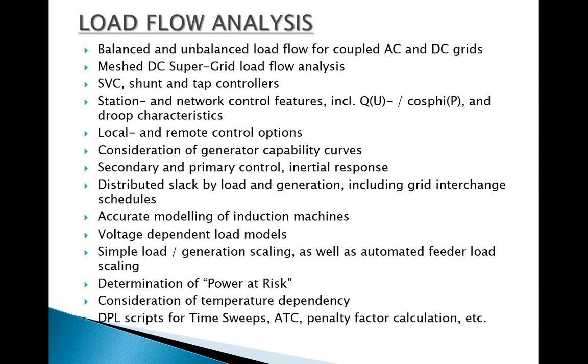Consideration of generation capability curves with the help of secondary and primary controlling. Initial response can be generated. Distributed slack by load and generation, including grid interchange schedules, can be done. Accurate modeling of induction machines. Voltage dependent load models are there. Simple load generation scaling as well as automated feeder load scaling, that kind of test can be conducted.